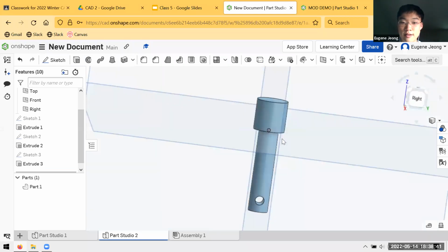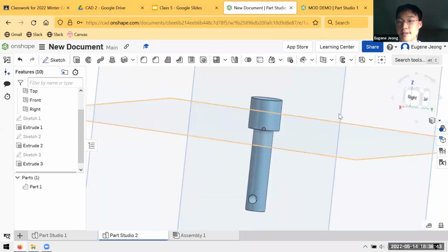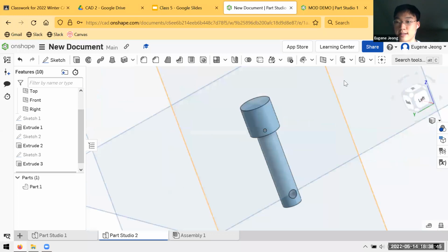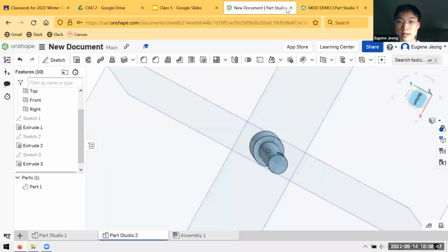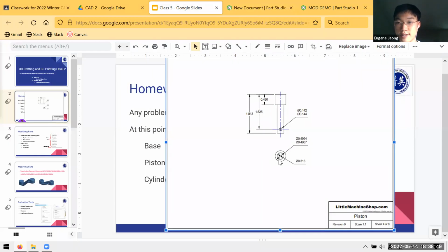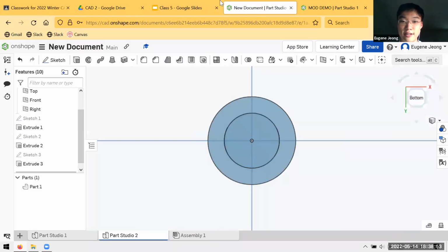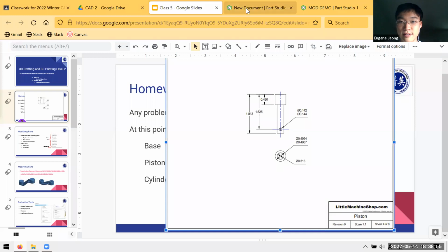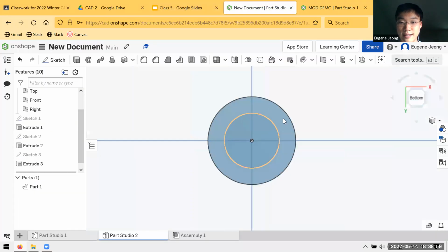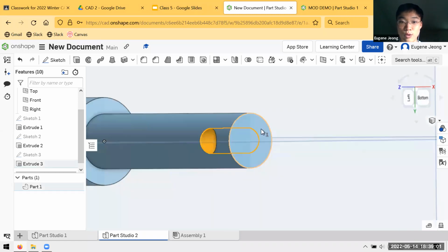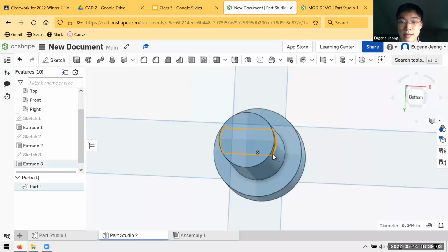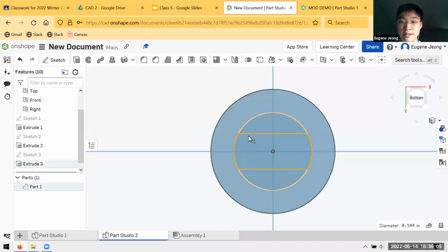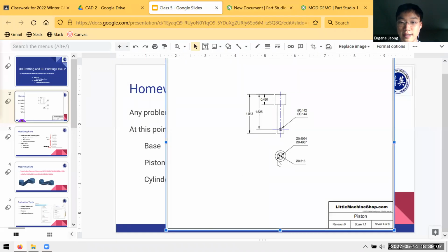And this is basically it. This is what the final part looks like. So you can see this bottom view. I know it's not the most clear thing in the world, but hopefully comparing these side by side, you can imagine this is the big circle, solid line. This is a little circle, it's a solid line. And then the thing that we can't see, this hole, becomes that dashed pair of lines that goes straight through.